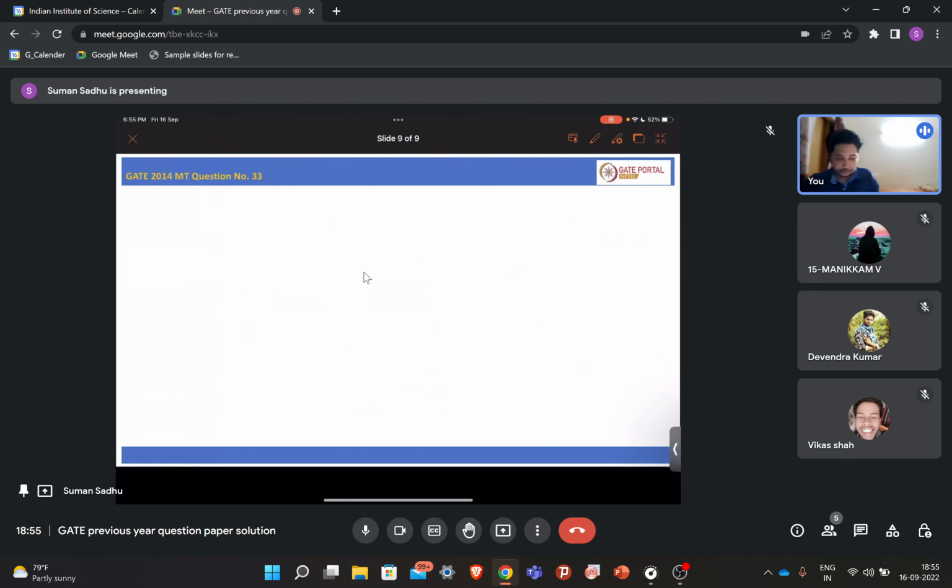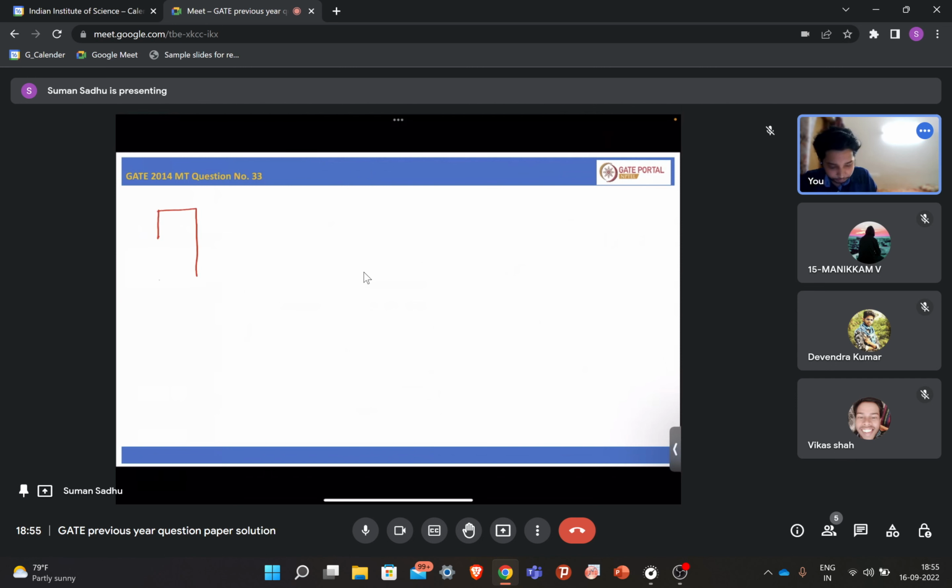Okay, so let's say this is your sample. It has a very sharp crack. That's the edge crack. Now, if you load this sample, so this is sigma. Your stress at a very large distance from the crack will be a straight line only. But when this stress line comes near the crack, it will bend because of the unavailability of the material or unavailability of the path.